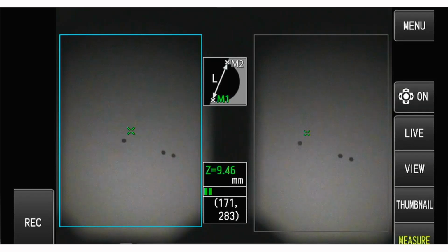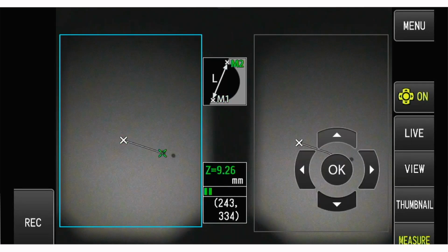So what you see here is the image from the video scope directly inside the check tool. It's just a plate with holes drilled at different distances. The special thing is that these holes were drilled at specific distances that were measured with very high accuracy, with equipment that's calibrated to international standards. So what we do here is measure the distance between 2 points, and this distance has to be really close to what is stated in the manual, or on a small label on the check block.